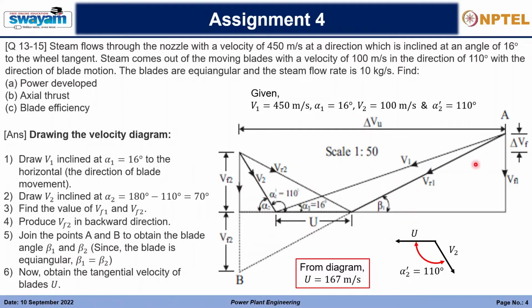So that is how we are drawing the velocity vectors, but we do not exactly need the velocity vectors in solving these 3 options that we are having. But we need this particular point at which it is coinciding with this horizontal line, because when we observe this distance, that is the blade velocity, right? If we do not know where this point coincides with this horizontal line, we will be unsure about the velocity. So we need to first calculate the relative velocity which is coinciding at this particular point. After that we'll get the blade velocity from here.